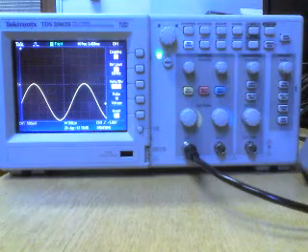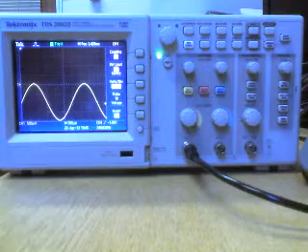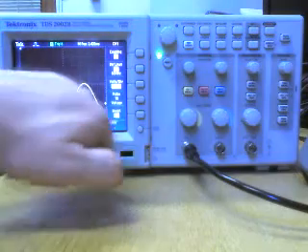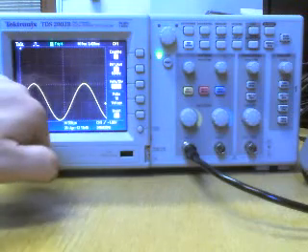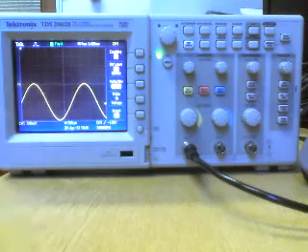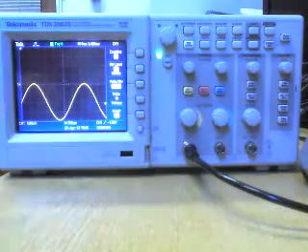We have a nice stable waveform. It's still scrolling across the screen, but it's been synchronized to this spot where the waveform starts, where we've moved our horizontal position to our triggered position, and we can measure it in much the same way as before.